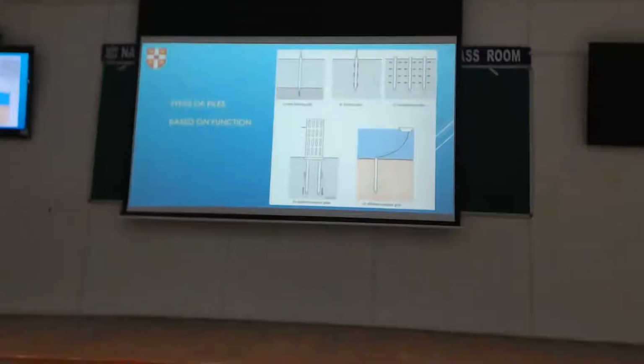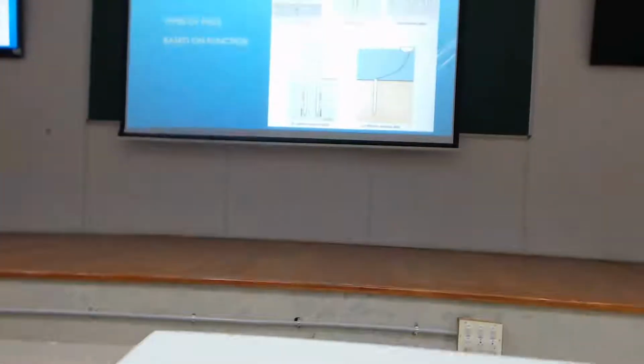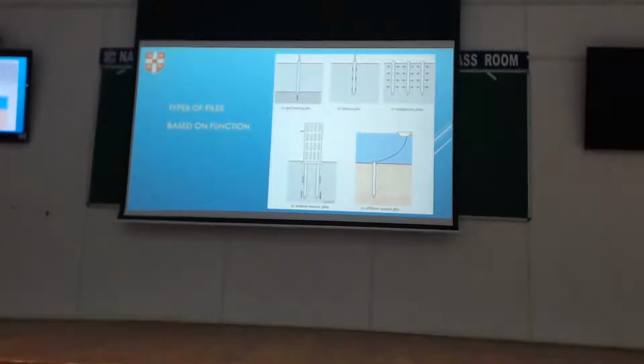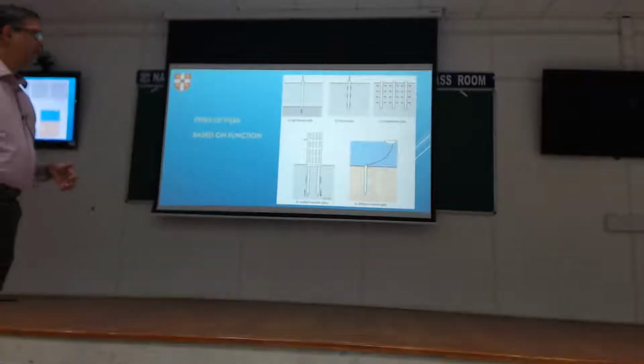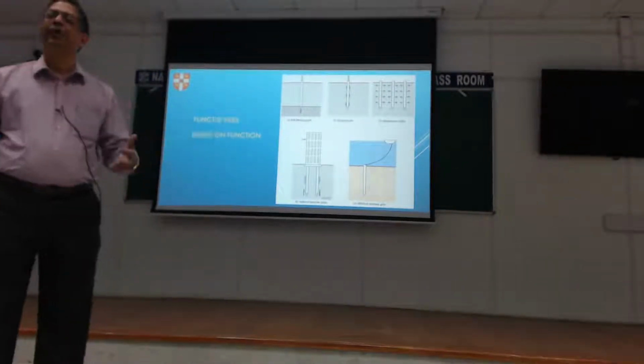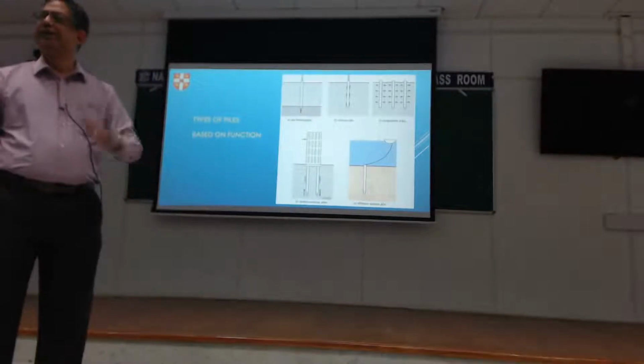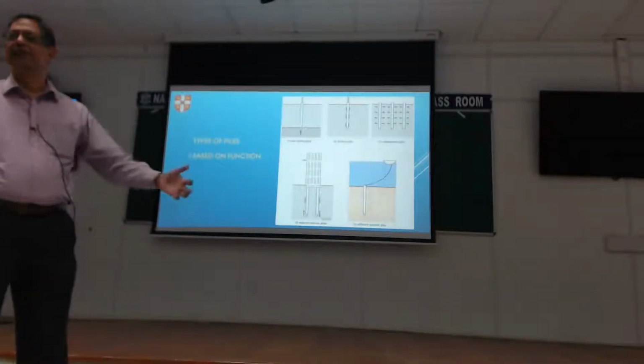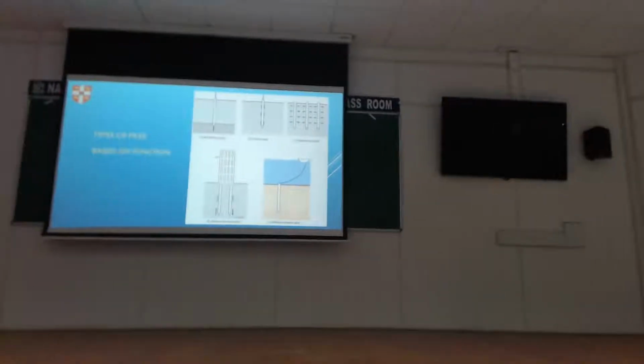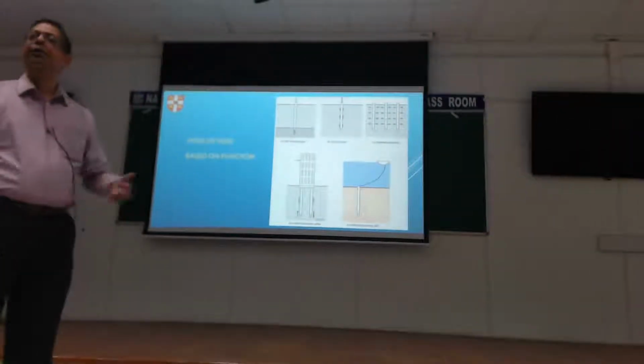Then you have to design the piles to carry everything more or less as skin friction, especially for piles in Kandla port and so on, where the stiff layers are really, really deep. You basically make the piles big and get the skin friction there. Sometimes piles are also not used for load carrying at all. You just use the piles as a means of ground improvement.